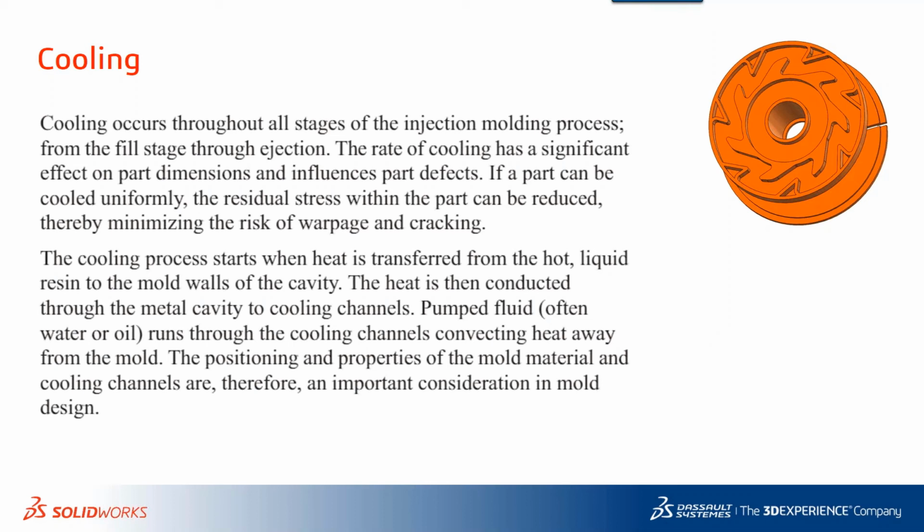It's always going to be there, and that's going to be your forced convection. So depending on the type of coolant that you're using, your cooling line shape, your cooling line diameter, whether you're including baffles, you can help with that cooling scenario.